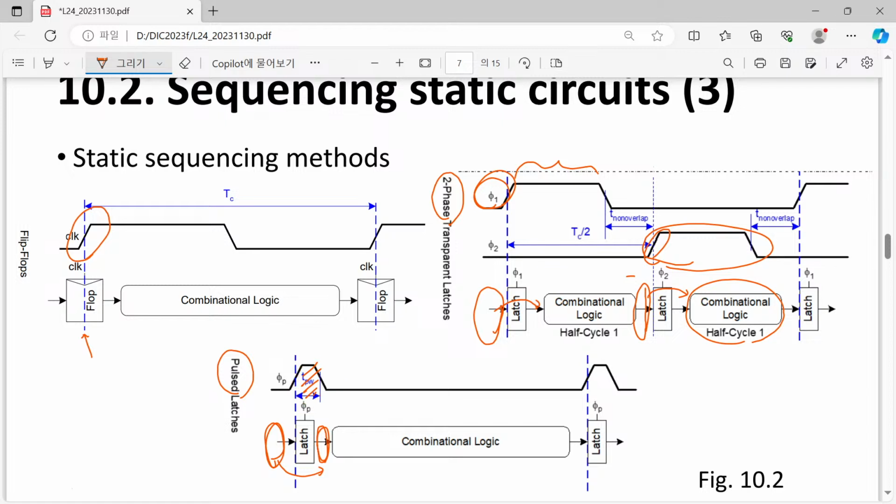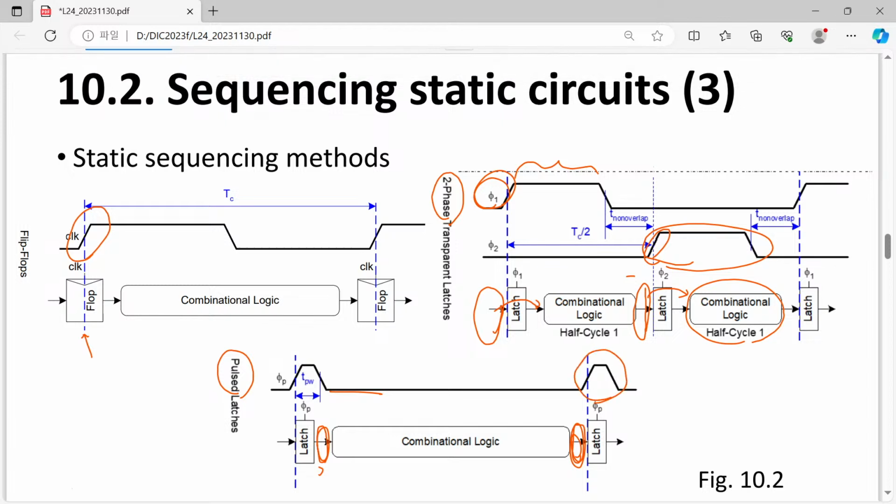After that, the clock becomes 0, so it is no longer connected to our input signal, and that is processed and we have an output signal some time later. And this pulsed clock is also used to send it to the next stage. So simply speaking, although the implementations are different, the basic principle is quite easy. I mean, prepare our input data, then just open the door for a while and sense it.